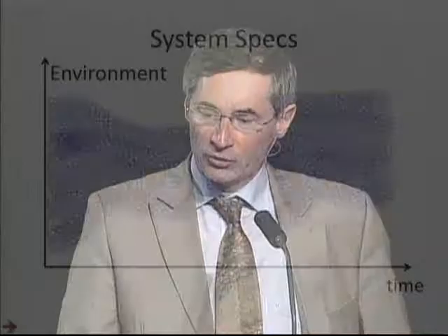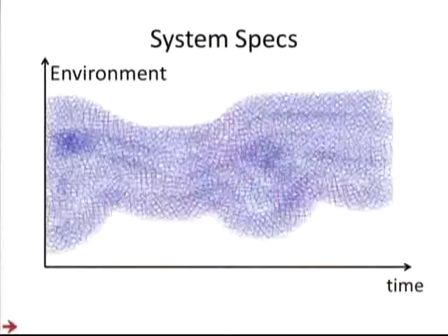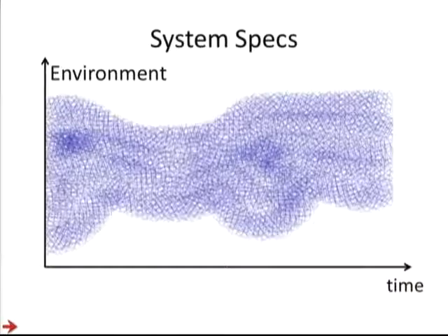So the transistors themselves that are subject to usage are actually degrading over time. There is elaborate effects that I won't go into detail right now, like NBTI or hot carrier or TDDB, that actually make it such that over time the chip degrades and basically the VT goes up and the performance goes down. So this is basically all what we have to deal with.